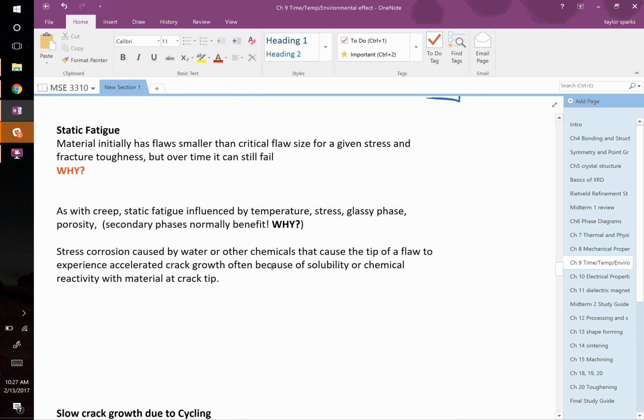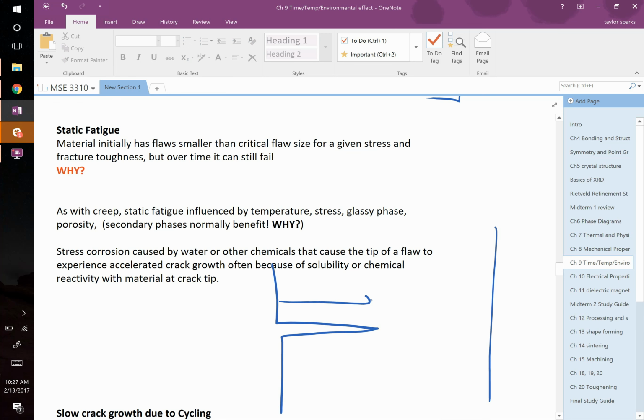You had your material, right? Your crack length was a, since it's a surface crack, that's your half crack length. But what's happening is that even if it's not underwater, there's a little bit of water vapor in air, right? And thermodynamically on small surfaces, water will condense right here, right? So you'll actually get water right there. So that thing is all now water.